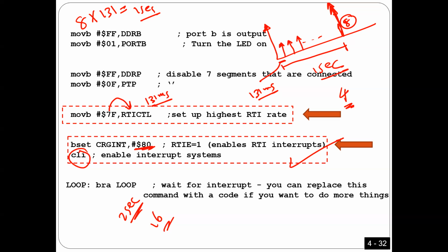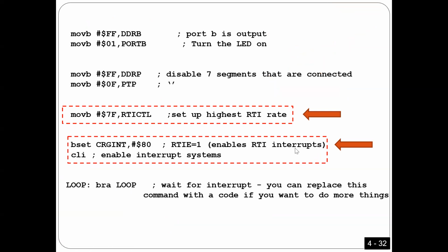So all I'm going to do, guys, if there is an interrupt, I should have a counter to count. This is interrupt number 1, number 2, number 3, number 4, and so on. And then I have to take action at a certain number. And then you have to clear the counter again, as we see right now. So look here. That's what I'm going to do. Now I finished the initialization this way, guys. This is the main program.